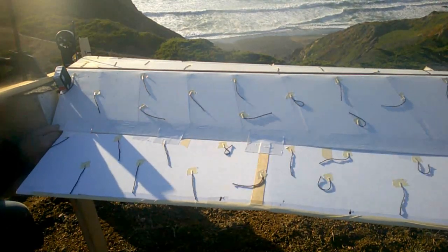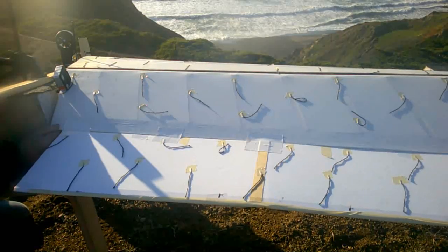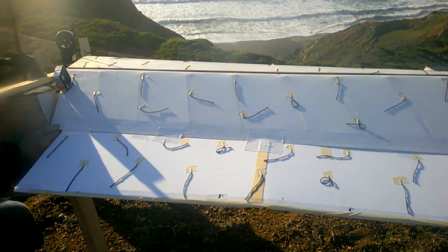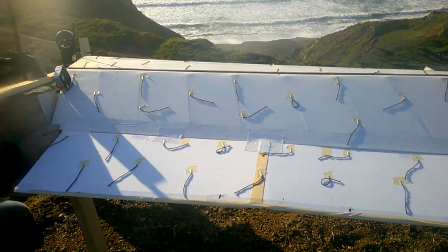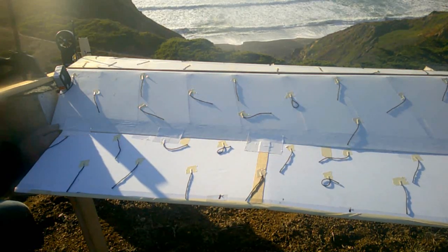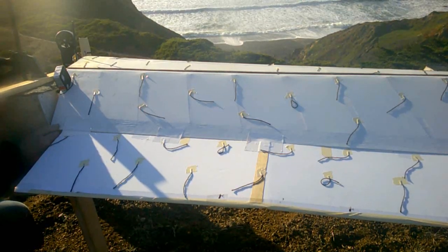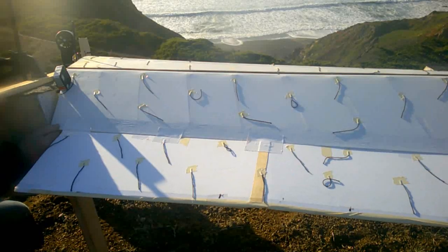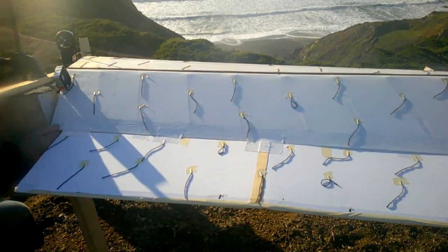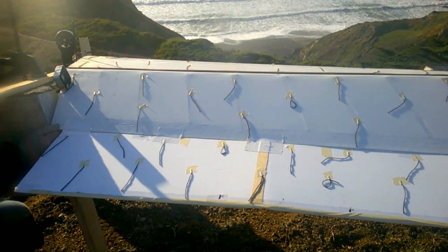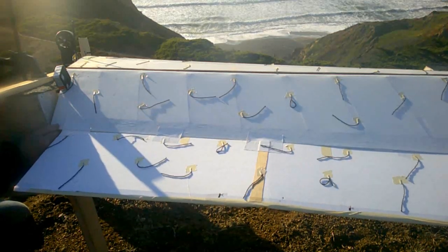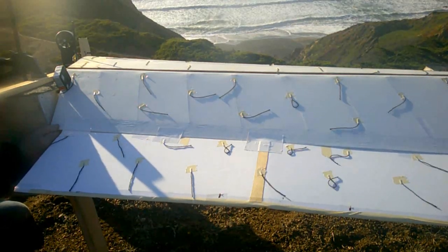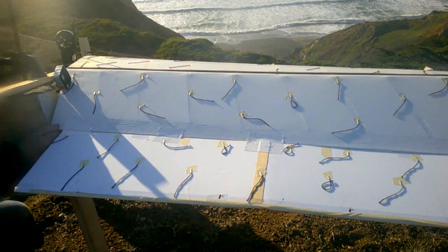Tufts turning backwards and forth. That would happen on any aileron or elevon at that deflection angle. Never going to get too much more than about 20-25 degrees before you have a problem. So by extending the chord and boosting the Reynolds number, I'm keeping the flow attached for an additional 10 degrees of elevon deflection, which is a good thing.